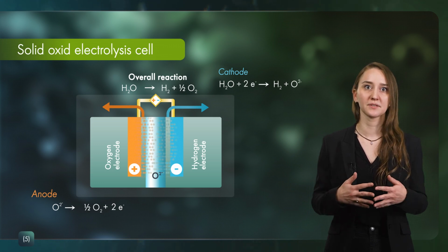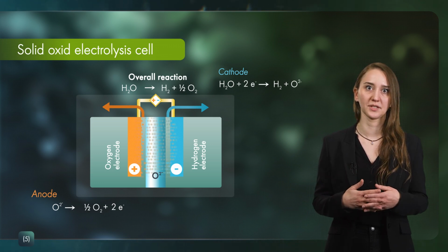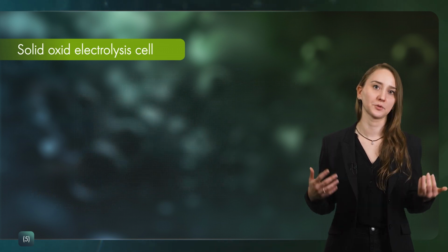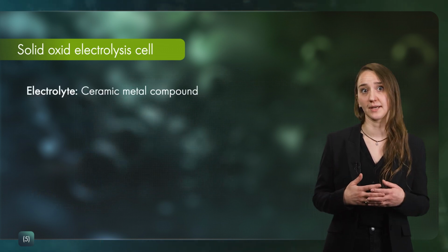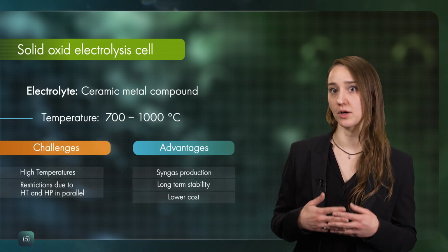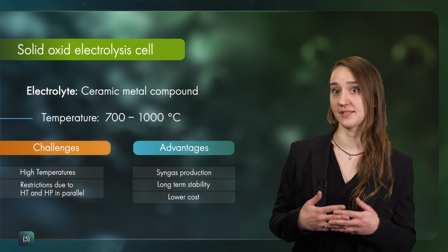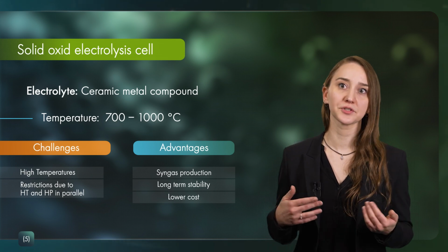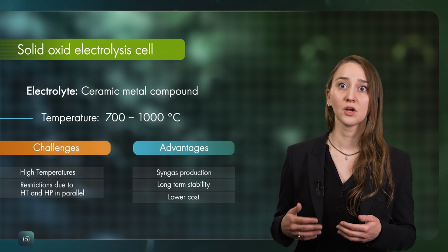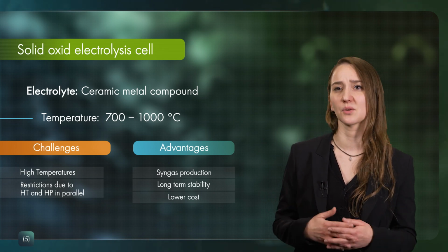The materials that are being used in this technology are, despite the high temperatures, fairly cheap and, if operated right, stable over a long time. Also, due to the high temperature, not only water can be split, and the efficiency is high. But the high temperatures are also a limitation. Pressurization is hardly possible, thermal stress is an issue, and so is dynamic operation.